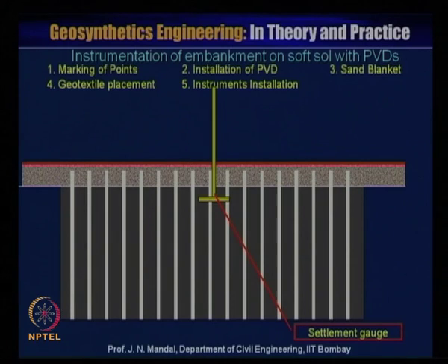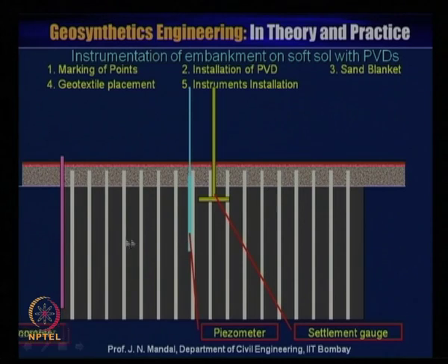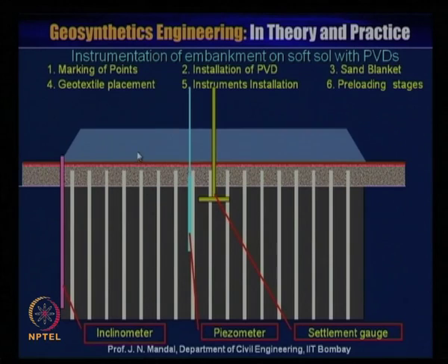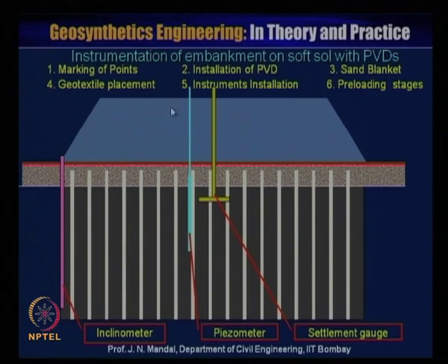You have to provide the settlement gauge. Next, you have to provide the piezometer here to measure the pore water pressure. Then you have to provide the inclinometer here. Then you need the preloading: you put the surcharge load, then there will be dissipation of excess pore water pressure, and the preloading stage is required in 1, 2, 3 stages.